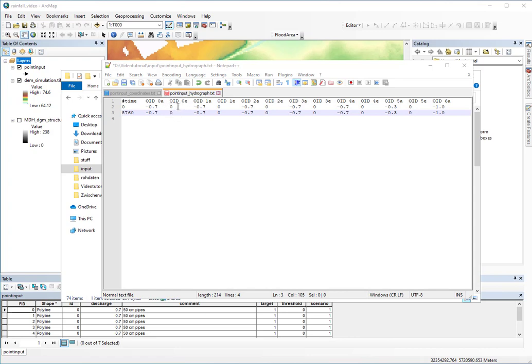And the 0 under the endpoint just indicates that there's no water taken, but only injected water that it gets from the beginning point. And you can see that it's the case for nearly all of our lines, except for our last line, number 6, the one that went in the sewer system, and there's only a beginning point, and it extracts 1 cubic meter per second, and has no end point where it is injected, so the water just leaves the simulation.